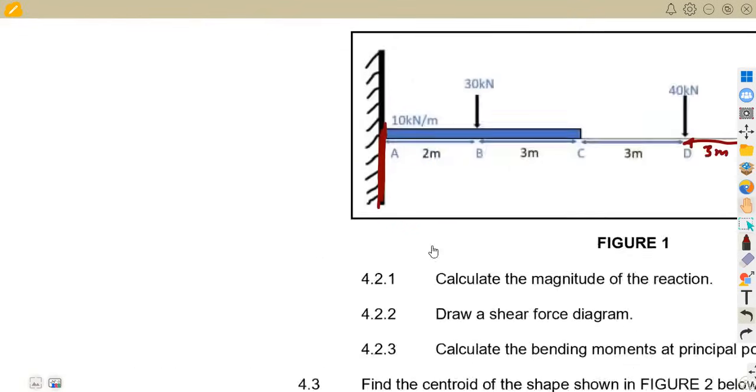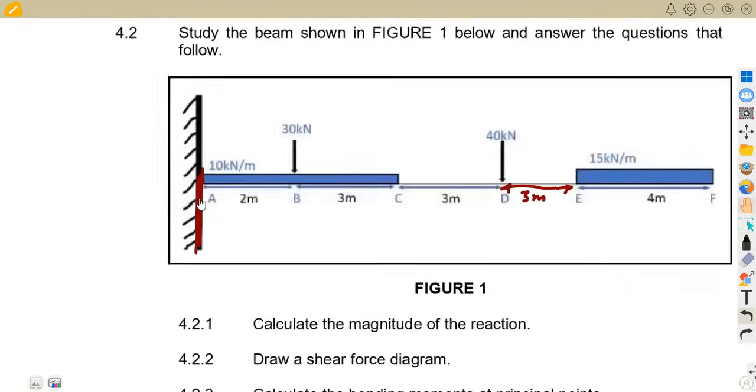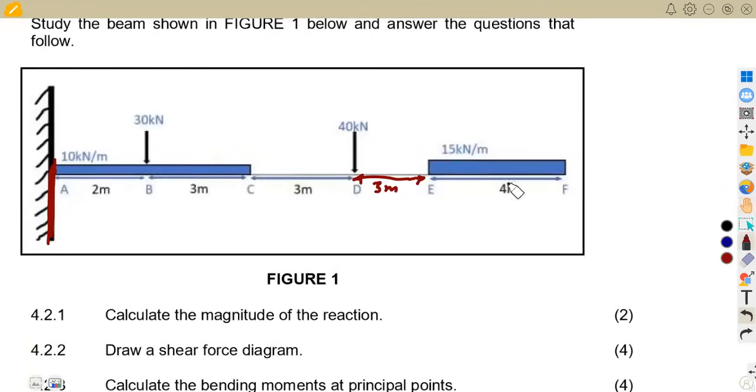Remember the bending moment is simply force times distance, all right? So that's 4.23. We've got the bending moment at A in this case. So at A, what is it that is going to affect? We have got a distributed load here, which is taken back to A. This distributed load is going to be affecting 15 kilonewton between these 4 meters.